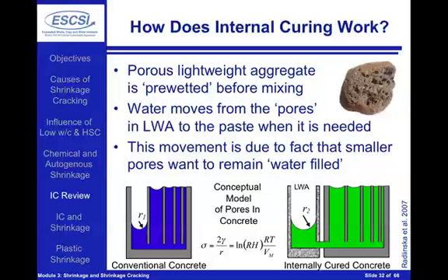The interesting part about this is that the water comes out of the lightweight aggregate at exactly the right time. Before the concrete sets, there's really not a pressure developing inside of the paste. There's really not a need for water to come out of the lightweight aggregate because the system can keep collapsing upon itself and we're not really creating a lot of vapor-filled spaces or under pressure that needs to be dealt with. However, after setting, once we've locked in the microstructure of our concrete, now all of a sudden we can supply water that's only going to help to reduce shrinkage and increase the hydration. And this is like a trigger that says, okay, let's start taking water out of the lightweight aggregate and let's start internally curing our concrete.